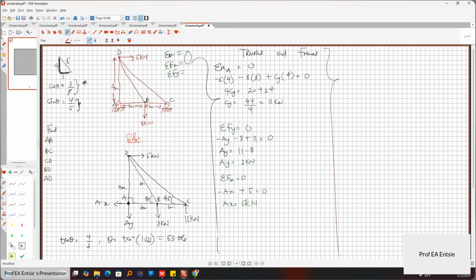So now we'll go again. Now that we know all the forces, we can place them there instead of AY, AX, and those things. So I'll bring it here. What did I get for AY? I had 3. Then AX, I had 5. So you take joint by joint because you're using the method of joints. Let's start with joint A.